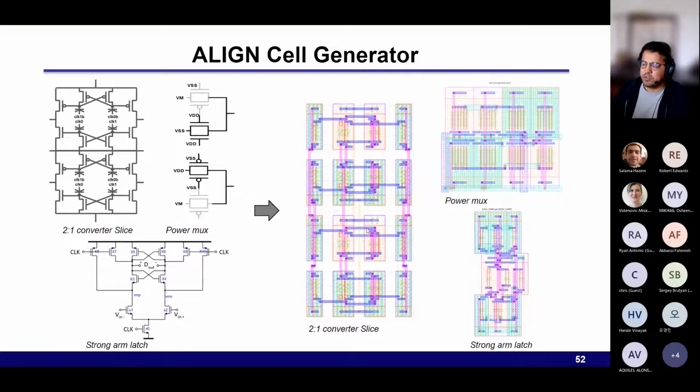And the reason is because you have PMOS and NMOS switches, and either you place them as a standard cell, which is much more dense, or you need to find a way to tell the constraints that you need a little more density here. The other block is the StrongARM latch that doesn't look really great, but it gets you a layout out. So we're trying to work with Sachin's student to improve this generation here.